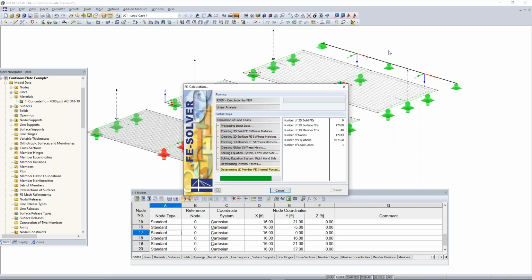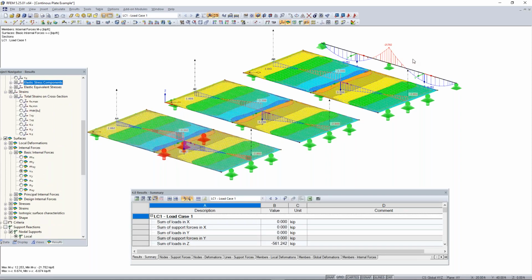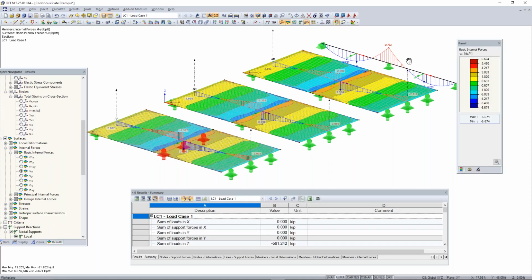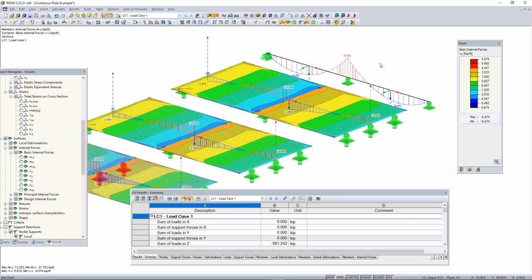before we were getting about negative 21.2 kip feet on our beam here. And so now we should be seeing something smaller. So this mostly needs to be turned off because the methods used in school assume an infinite shear stiffness when in reality there are some shear deformations happening when the member bends here. So you need to keep this in mind when comparing hand calculations of deformations in RFEM.